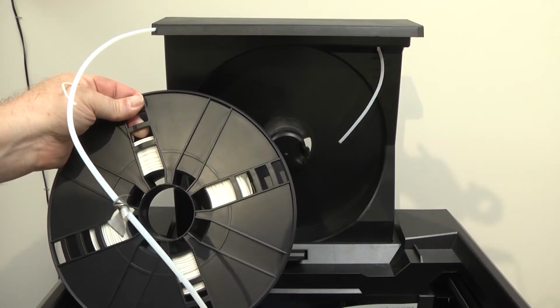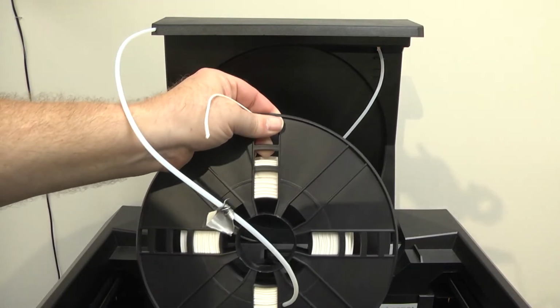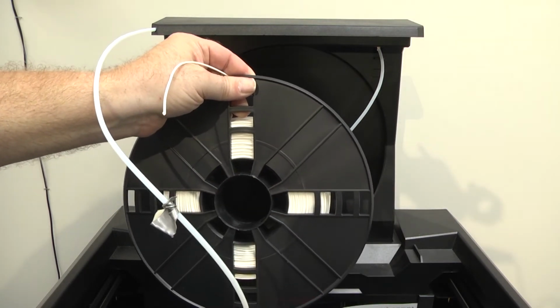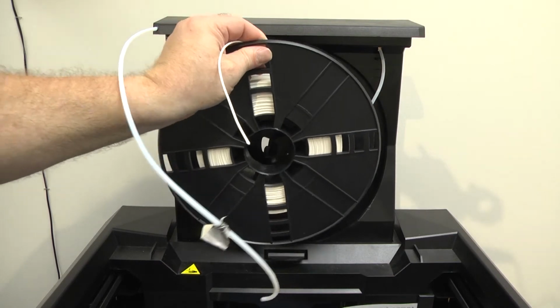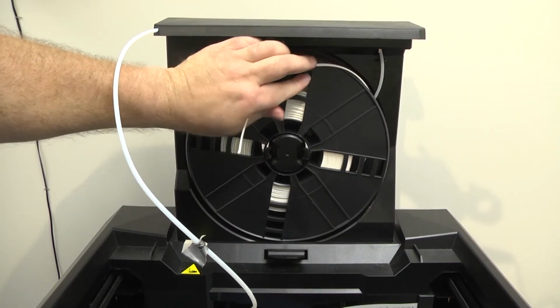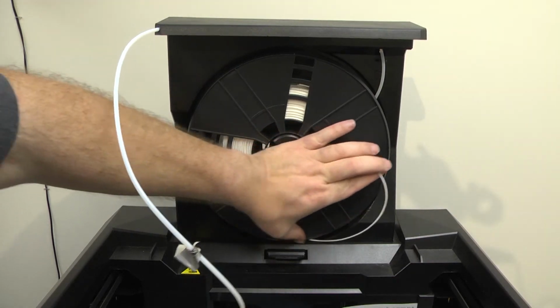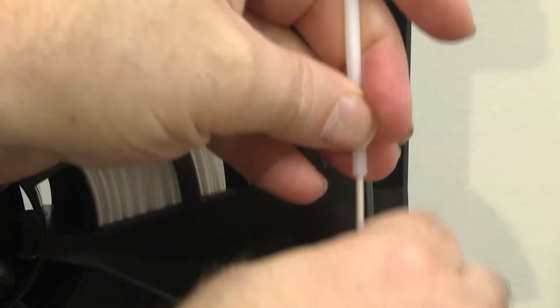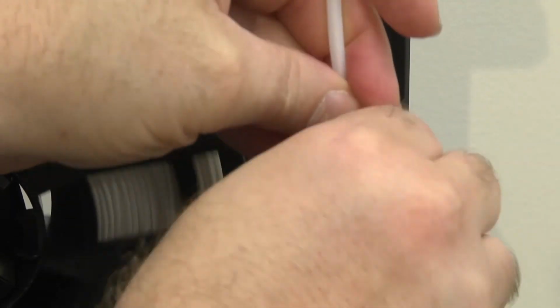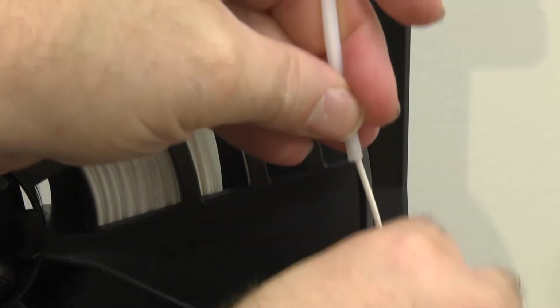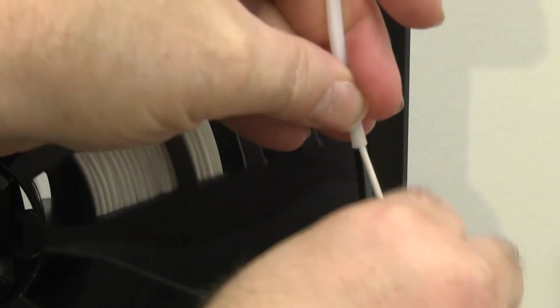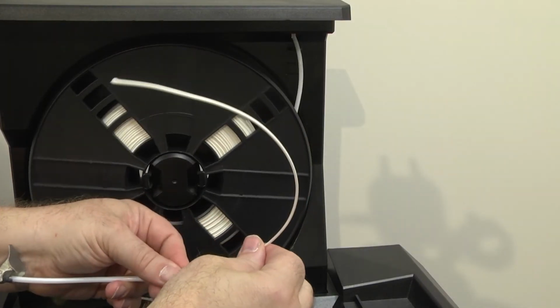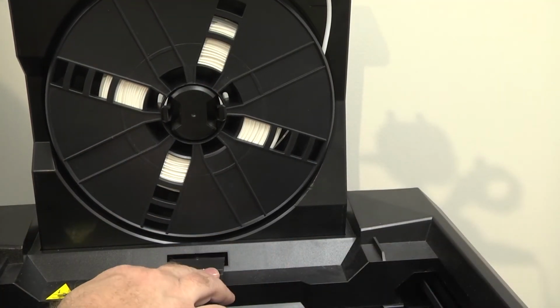The first thing to do is to put the filament onto the spool. Be careful to hold the end of the filament. Don't let it unravel. If it gets tangled, it will jam. Make sure to free the straw. Very carefully thread the filament into the straw. Keep threading it in until it comes out the other end. When you have done this, take the other end and pull it taut. Then hold the spool, push the lever, and gently lower the cassette down.